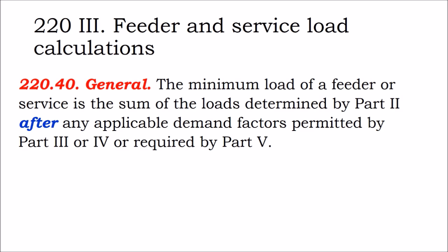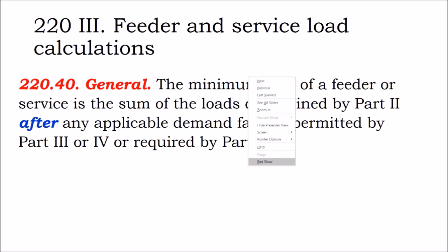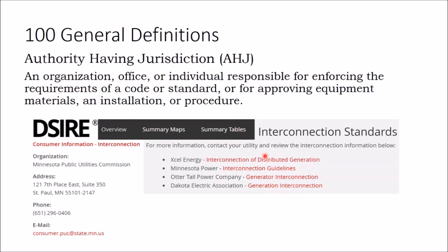Now, if you calculate all those appliances, you get to your dwelling unit, and the minimum load for that service is determined by rules and regulations and not necessarily your individual client's electric use. And so you might find that your client only needs 10 amps of power, and a Tesla Powerwall is 10 amps of power.